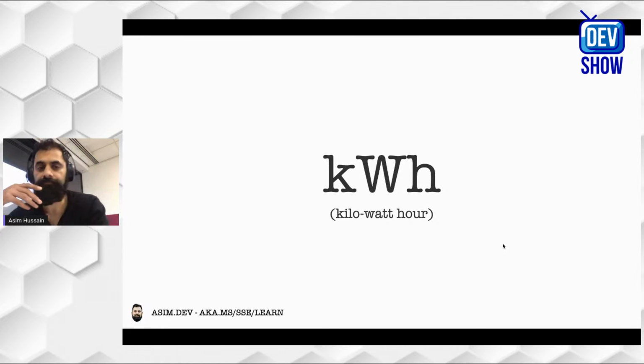It's quite important. The standard unit of energy is called a joule, and it defines a volume of energy. A watt is a rate. A watt means 1 joule per second. A kilowatt, therefore, is 1,000 joules per second. But a kilowatt hour is a volume of electricity. It's how much electricity you would have if you ran that for 1 hour. So you often hear people talk about kilowatt hours, and what they mean is a volume of energy.